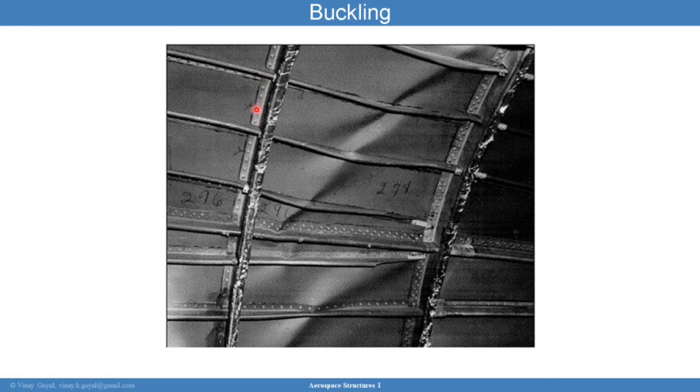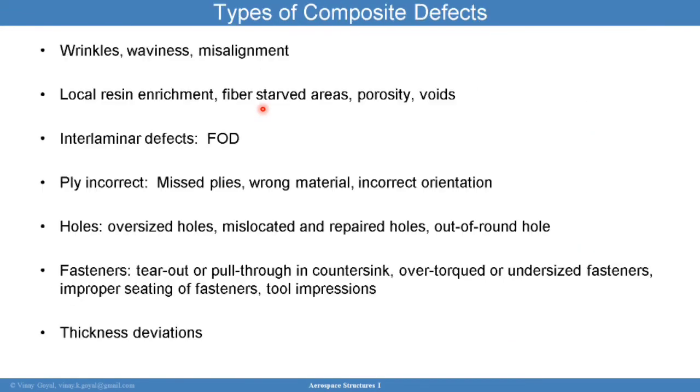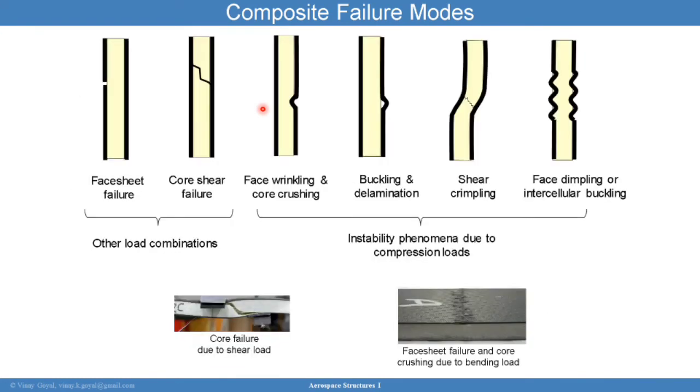You may not have bolts, so it will be co-cured, meaning bonded to some level, where the resin from the stiffening side and the composite fuselage skin, the resin between the two bond together. They form polymeric links. If you have defects in between, those could now be sources of failure and delamination. A lot of testing is going on in industry to better understand these failure modes.